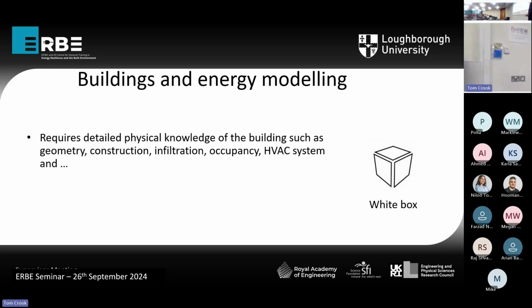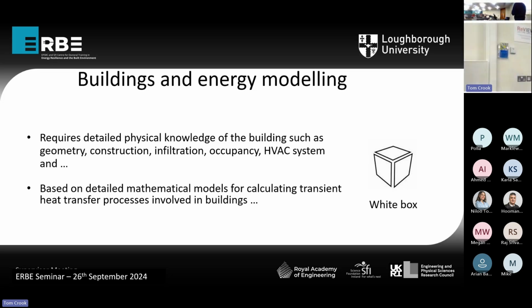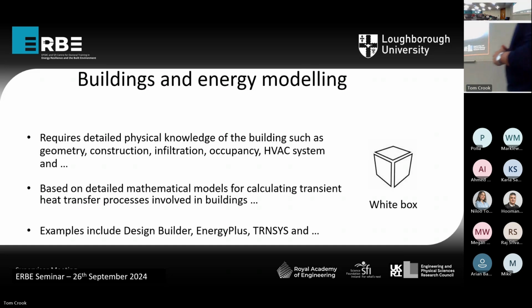As you know, I'm working on the applicability of gray box modeling technique on passive house buildings in the UK. Just as a quick reminder, modeling is widely used in building energy research. In the classical sense, like George talked a lot, we use the white box approach, which requires detailed physical knowledge of the building, such as geometry, construction, infiltration rate, occupancy profile, and information about the HVAC system detail. Then we need detailed mathematical models for calculating transient and transfer processes involved in the building and predict, for example, indoor temperature or HVAC energy. Examples include DesignBuilder, EnergyPlus, and so on.